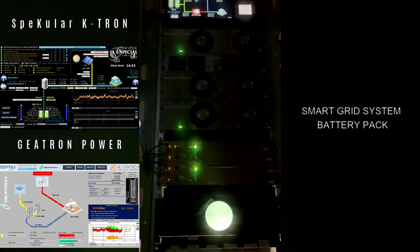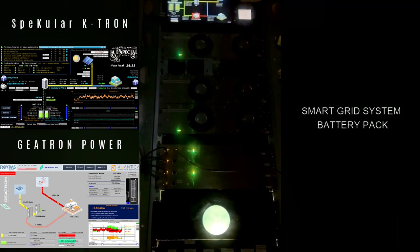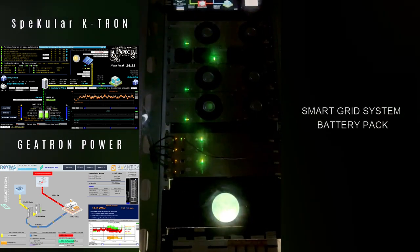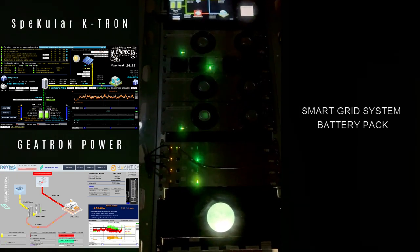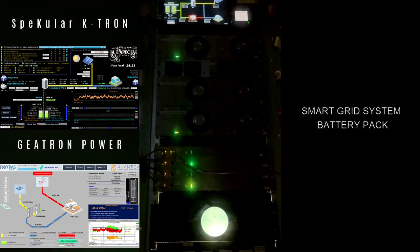Smart grid system, battery pack. Minimum cycle life of 6,000 cycles. Minimum lifetime of 10 years. Maximum discharge of 100%. Active balancing between batteries using DC-DC converters. Passive balancing between all cells that make up the battery using a BMS, battery management system.